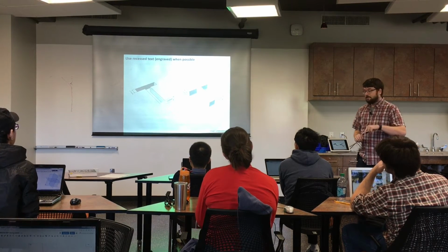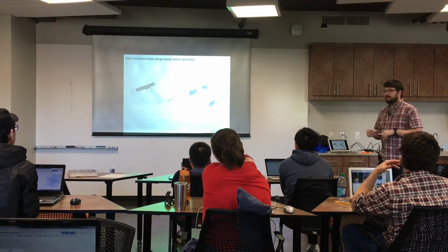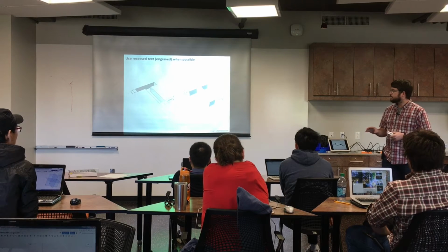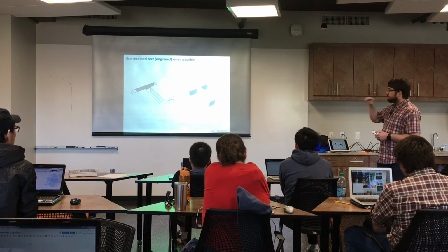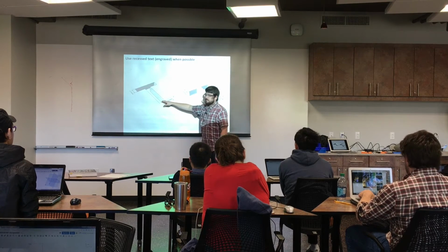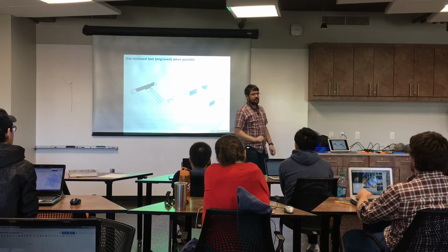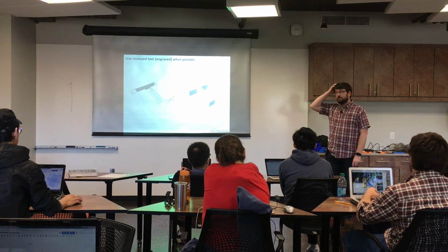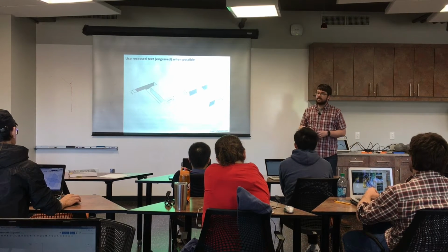You can put text on parts. We have a part in the lab that actually says rock mechanics on it that I 3D printed a long time ago for a lab. It has raised lettering, which is what we call embossed lettering, and this is engraved lettering. Generally, if your letters are not huge like those are, you want to go with engraved lettering.